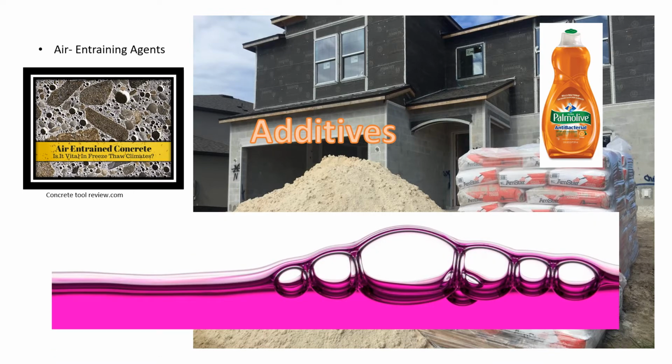Many feel adding liquid soap does the same thing, and to a point that is true. However, there are two reasons not to use soap in your plaster. First, manufacturers, particularly with blended products, will often already have added an air entrainer inside the blend. Having more air bubbles is a bad thing. Second, the soap is an uncontrolled air entrainer. This means it will not stop making bubbles as the material mixes. Think of dish soap and how whipping up that water just keeps the bubbles coming. This is what can happen to your plaster. Plaster base coats with excessive air bubbles will be very weak.